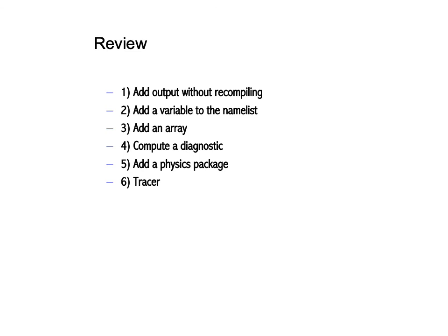A nice example is if you have a very long forecast with a very large data set. If you would like to see output for a few variables at very high frequency, you can add those variables into a separate output stream at whatever frequency you would like without over-encumbering your disk system on your machine. So you can have your meteorological data come out every 6 hours for your 10-year simulation, but have data every 5 minutes for something, for example, like precipitation.